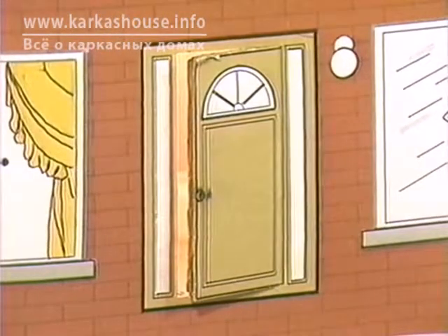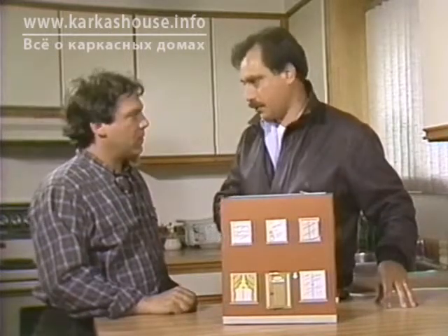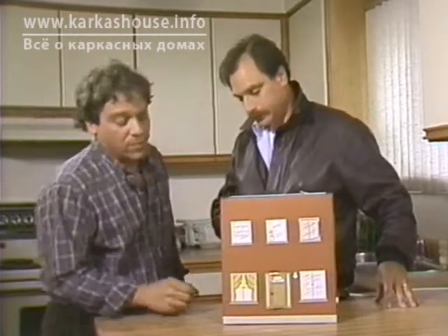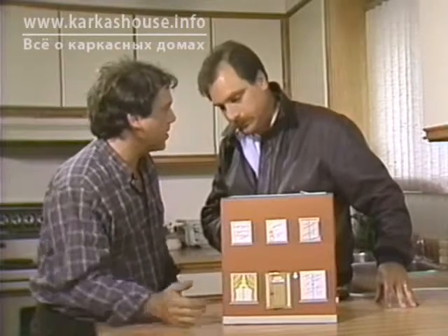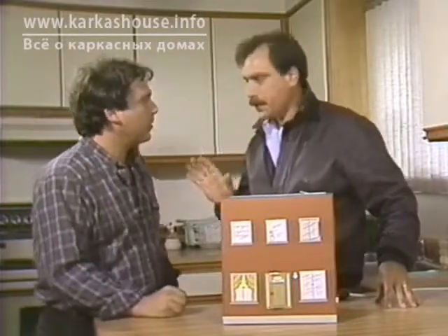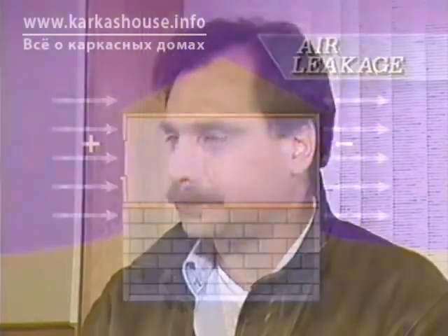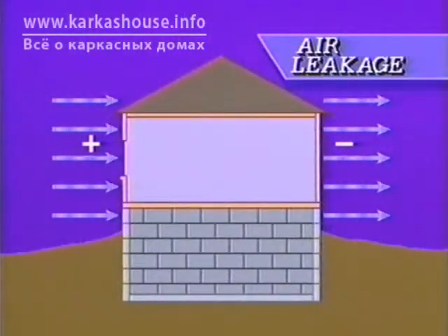What we have here is a cardboard model of a house, and we want to use that model to show how air leakage occurs in a building. Well, it's a fancy model, Oliver, but obviously the air leaks out of the cracks and all the openings in the building. Well, that's partially correct, but in order for it to leak one way or another across the barrier of the wall, there has to be some pressure. A pressure difference can provide the push or pull you need to create airflow through an opening.